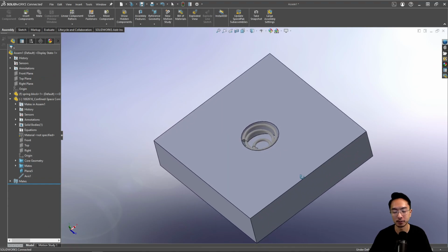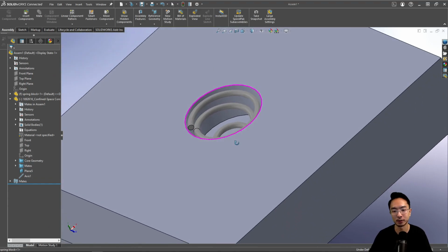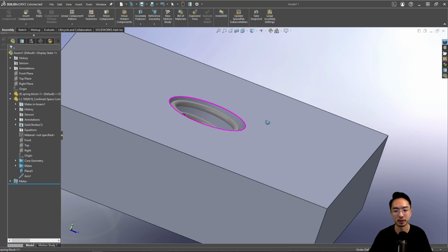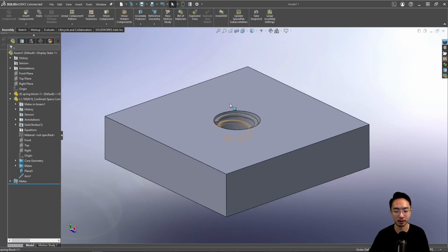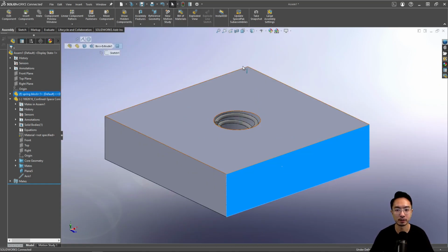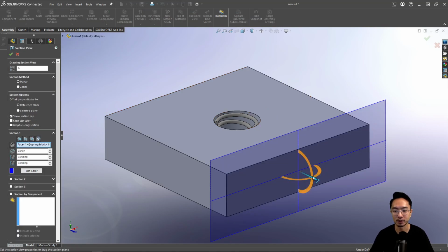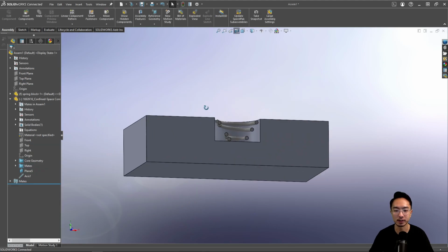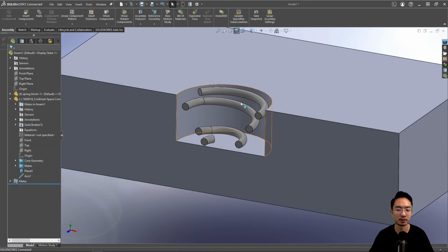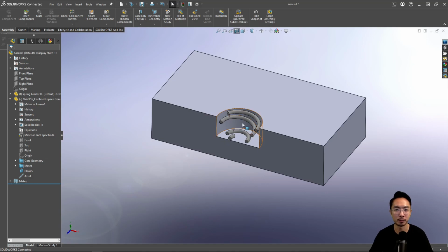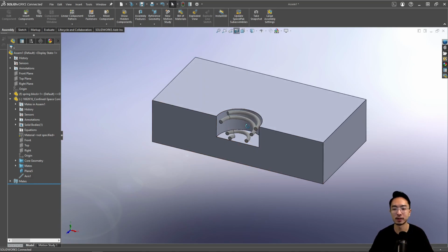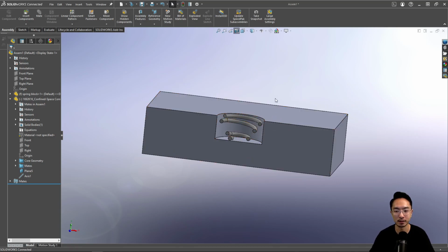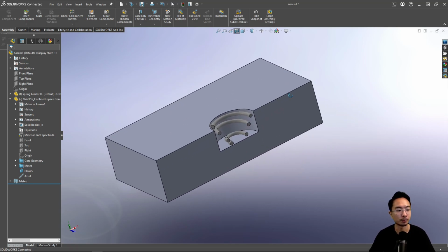And then, typically, like I said, you would have either the outer walls or inner walls to hold it. Here I'm using the outer walls. And then you might have something that goes on top of this block. Okay, so if I take a section view to see how this looks, you can see our spring inside our assembly. So there's a myriad of things you could do with this. Maybe you have a button. You could have something that goes on top that slides up and down, and then the spring will come down as it slides. Okay, so hopefully this gave you an idea how to put a spring inside an assembly.